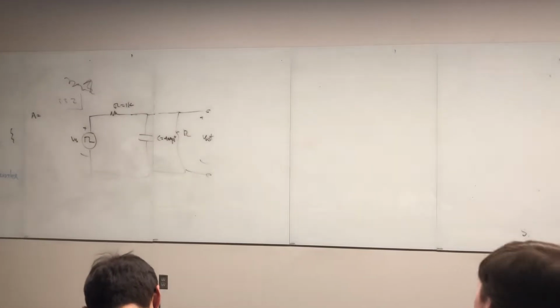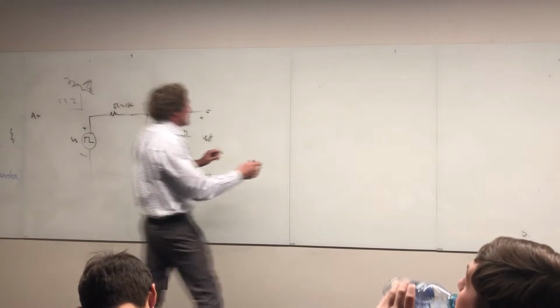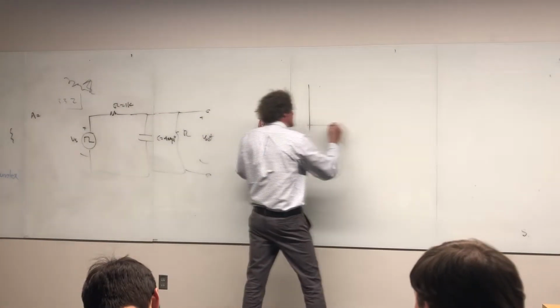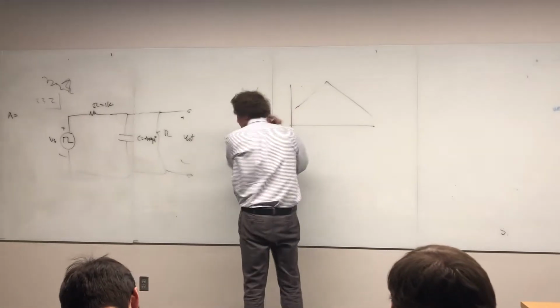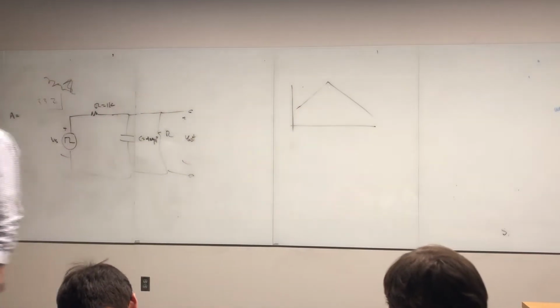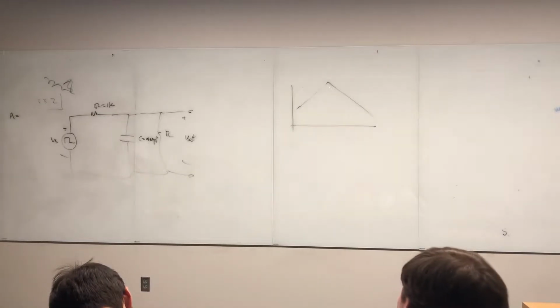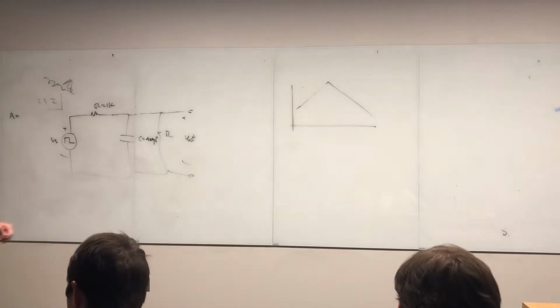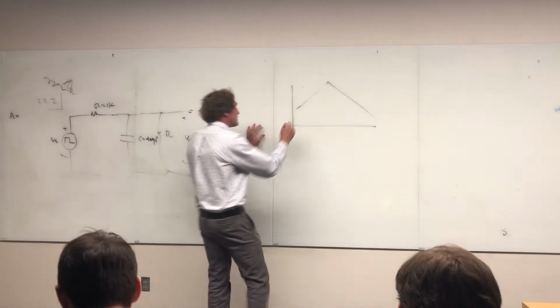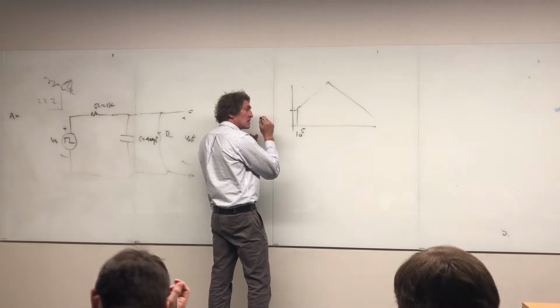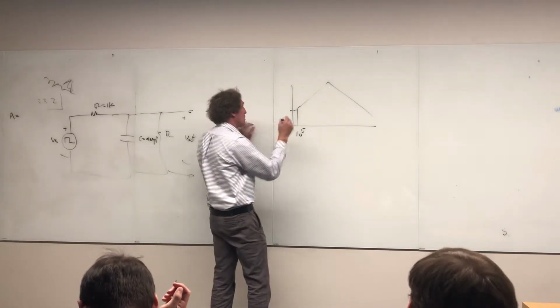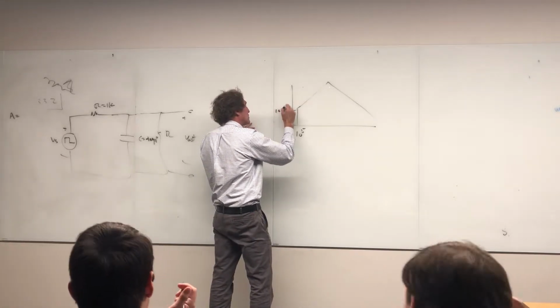I was hoping I just wrote it up. So for the input, and that is input, right? He has this kind of an envelope like this. What's the frequency, the low frequency he's got there? 100 dB. No, right here. Oh, is that 10 to the 5th? Yes. And at 10 to the 5th, what's the signal level? 100 dB. 100 dB microvolts, right? Correct.